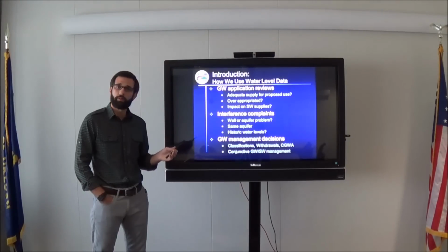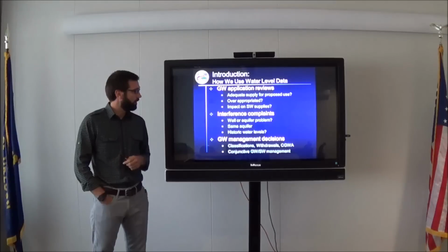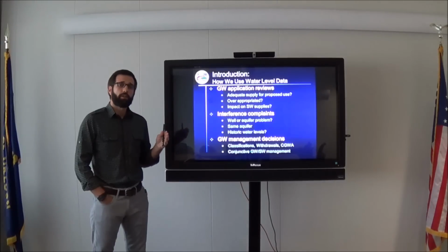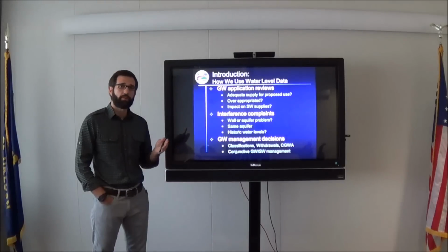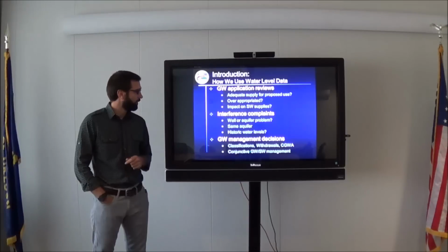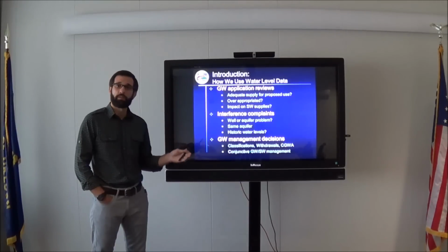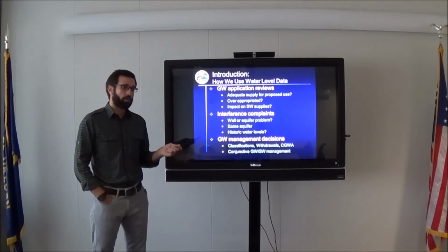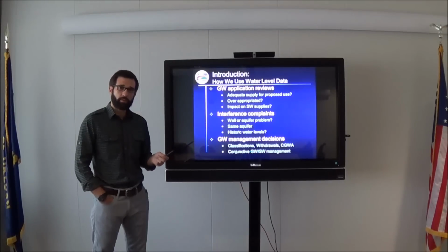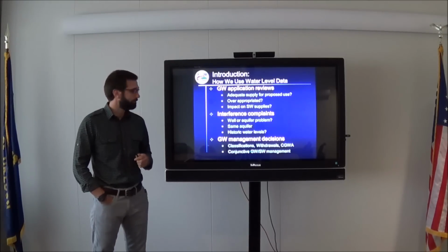Next, we use those in well-to-well interference complaints. So we look and see, is there a problem with the aquifer here? Are water levels declining in the aquifer? Or do we have a well that's inefficient and we're just having problems in an individual well? And we also look for same source in water levels. Are the heads drastically different in these wells, or are they producing from the same source? And so we use current water levels that are coming in. We also use historic water levels.